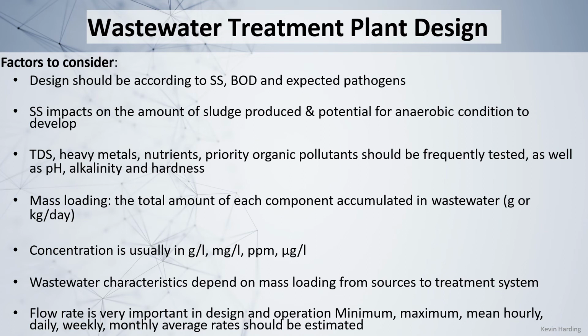The suspended solids are going to impact the amount of sludge we've produced, which we already said is going to be a concern generally in water that we are going to distribute out to rivers and out into the environment. So how are we going to deal with those? Total dissolved solids, heavy metals, and nutrients we also need to test for frequently, as well as pH, alkalinity, and hardness, because all of these items are going to be an issue with wastewater standards, as we said, for the legal side of things.